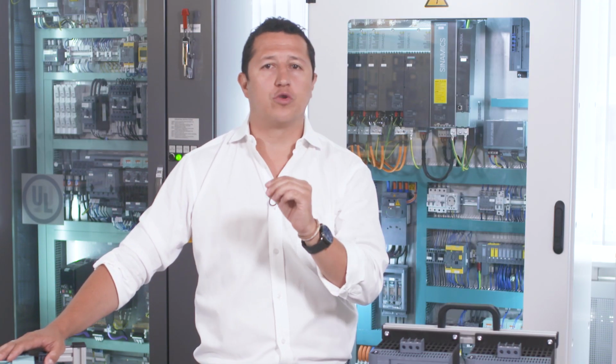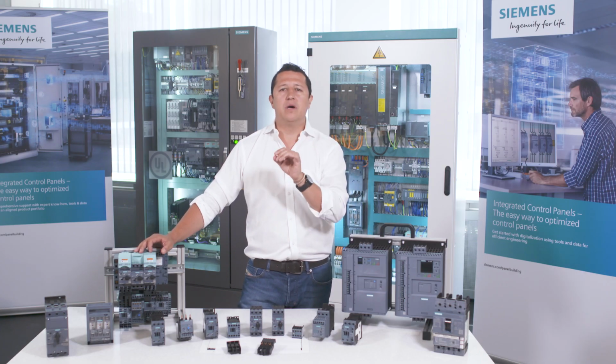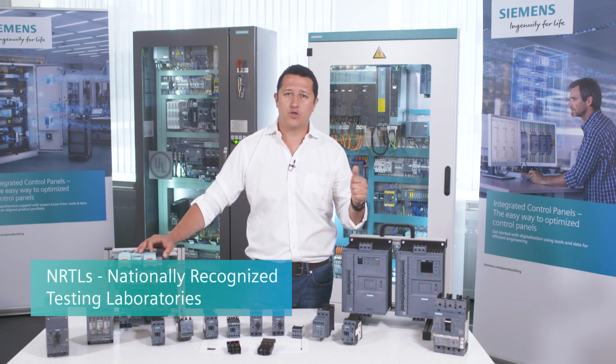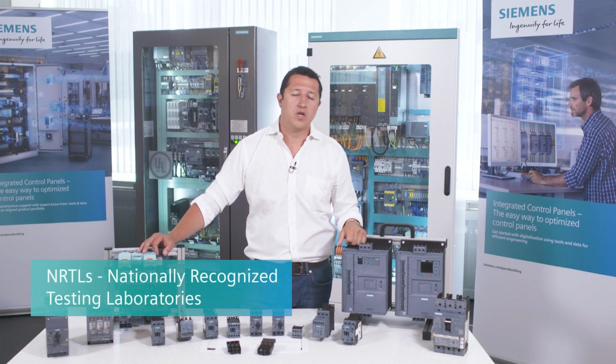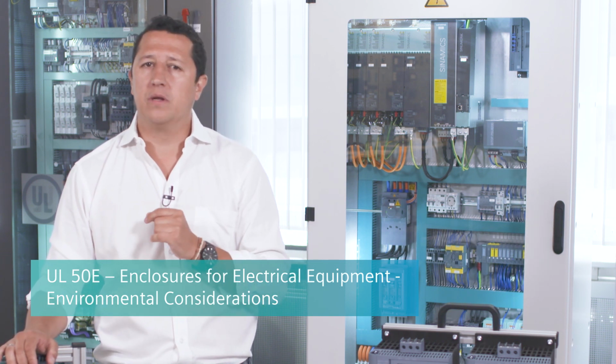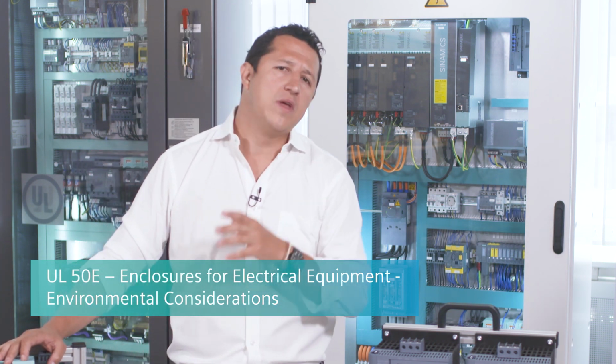NEMA is not a testing organization that tests enclosures for compliance with the standard. These tests must be done in the US by recognized test labs, or NRTLs, nationally recognized testing laboratories, such as UL, CSA, or others. The standard UL 50E, Enclosures for Electrical Equipment, Environmental Considerations, is actually applied for this testing.